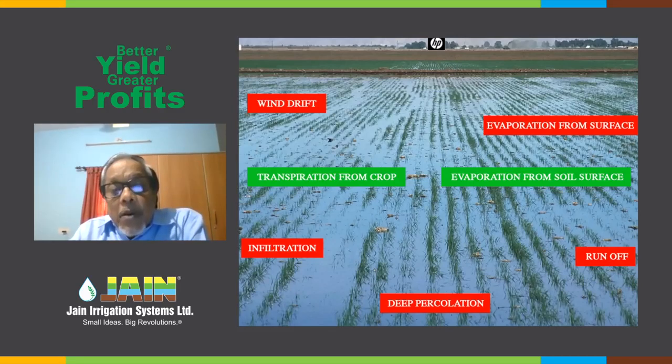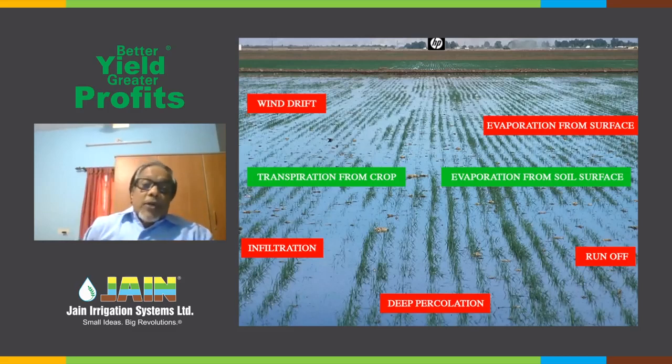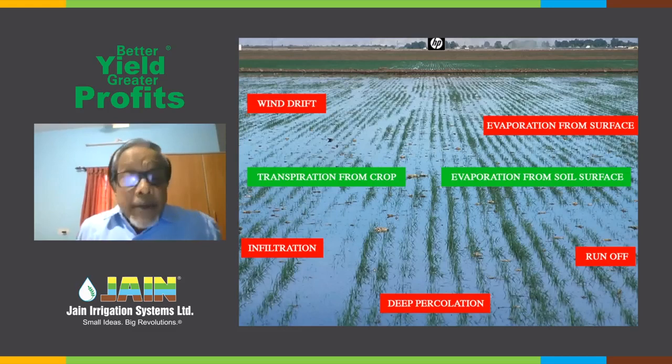Then there is a component where, wherever the field is exposed, even after the standing water comes down to the field level, the soil is exposed and the wetness from the soil gets evaporated. That's evaporation from the soil surface. So basically crop water use comes only from these two green things: evaporation from the soil surface and transpiration through the crop, or through the canopy of the crop.